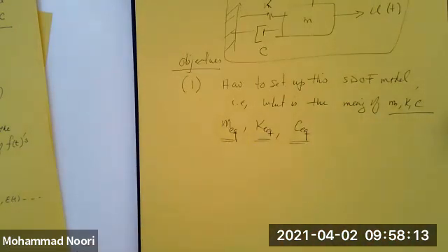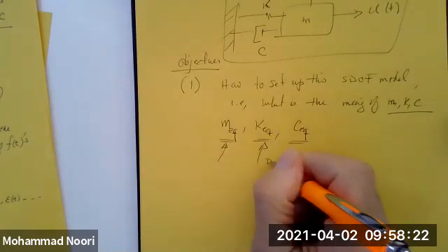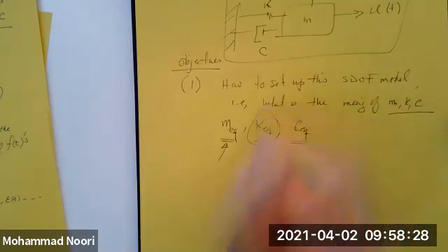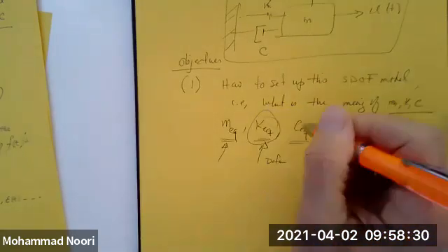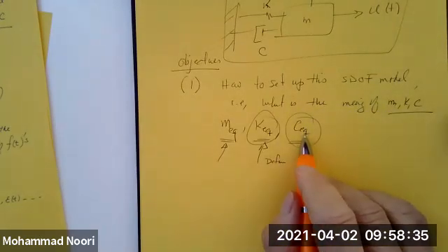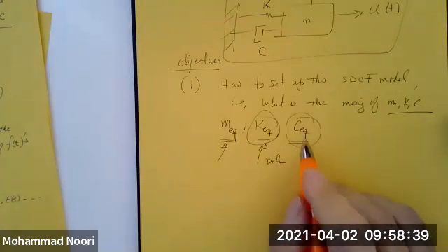In other words, if you have a big structure, what is the inertia in that structure? How does that structure deform statically under the action of a static load? Or what is the stiffness of that structure? And what is the damping force or damping coefficient or component, energy dissipation component in that structure?